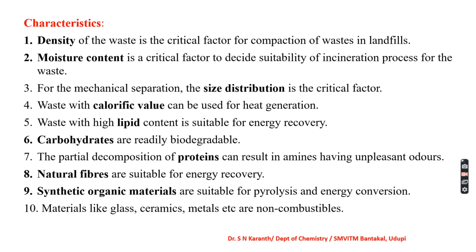Moisture content is a critical factor to decide the suitability of the incineration process for the waste. That is for the disposal method. What kind of method we have to choose depends upon their characteristics: density, moisture content, size distribution. Is mechanical separation possible? Sometimes we have to do a mechanical separation to remove the solid waste. The size distribution is the critical factor.